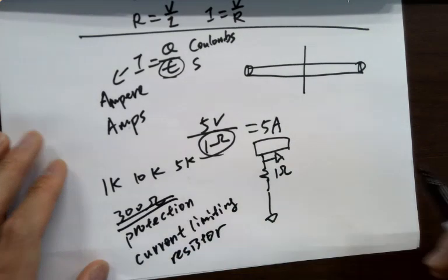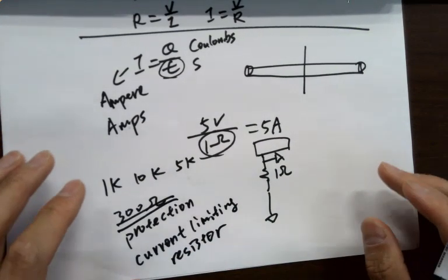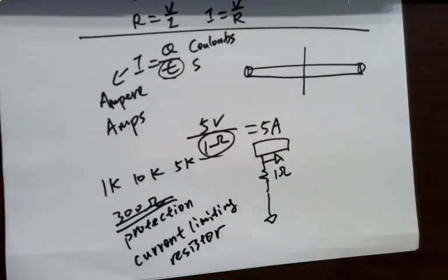So now this brings up another question: why do we need the resistors? It's a very big question. To make sure that we supply the correct amount of voltage to a component. Sure, that's definitely one of the correct answers. There are just so many ways to use resistors. You can use resistors in voltage dividers. You can use a shunt resistor. Yes. So you can deliver correct voltages. You can deliver correct currents as well.